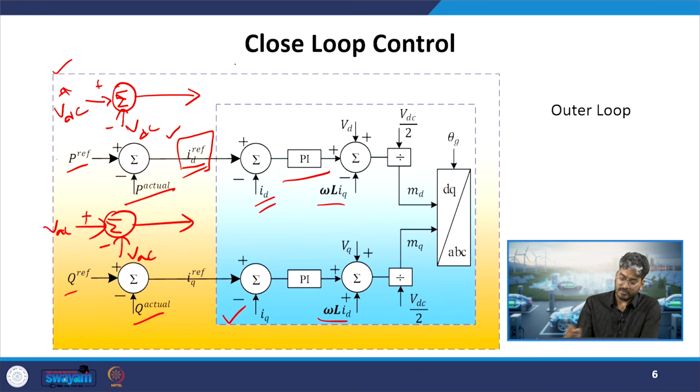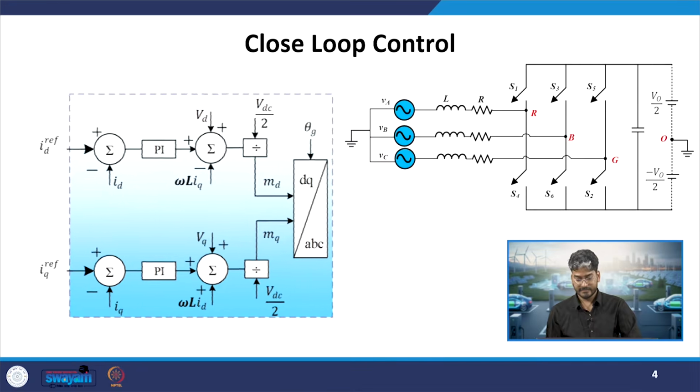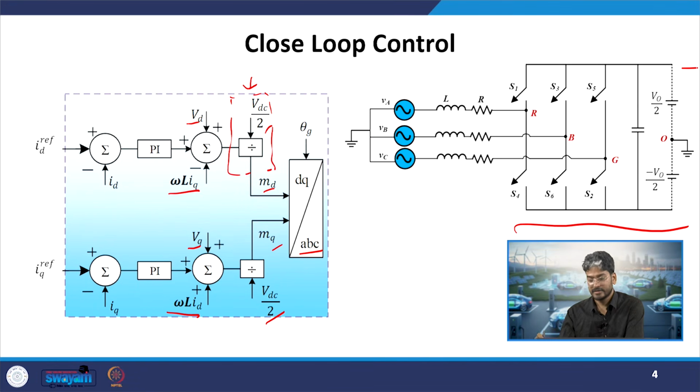Let us go back to this circuit. In this case, we will have a preceding stage which will be converting our DC bus signal. So, this is the DC bus. Okay. So, this will be the intermediate stage. After that, we will have a DC to DC converter which will be meeting the requirement of our battery voltage, because, as we have already discussed, the SOC of the battery will be changing, so its terminal voltage will be changing. So, now this DC to DC converter will be responsible for maintaining the difference between the DC bus and the actual requirement from the vehicle.